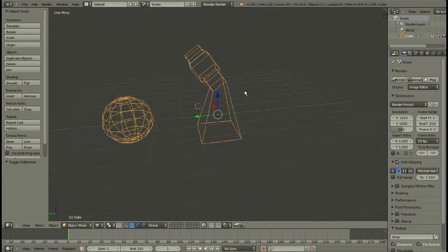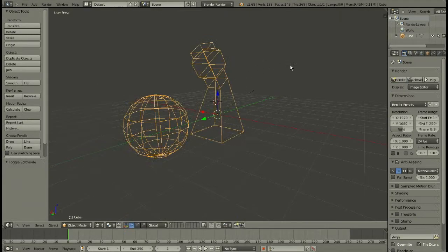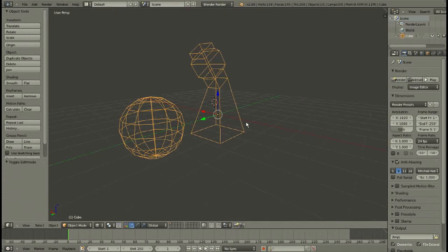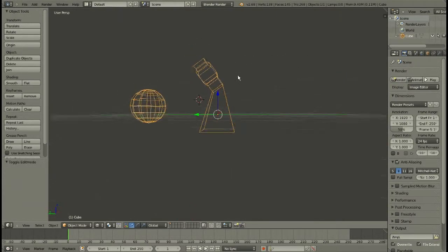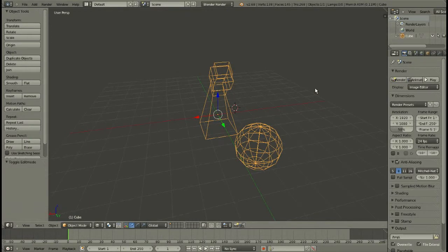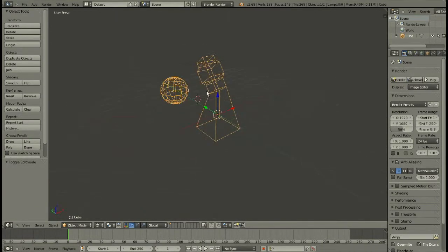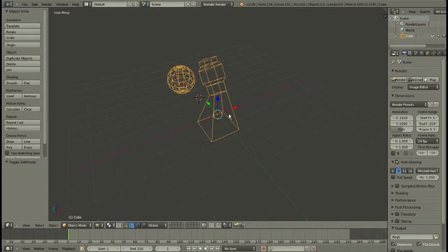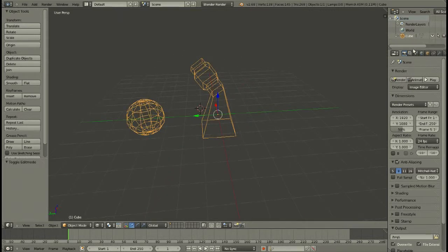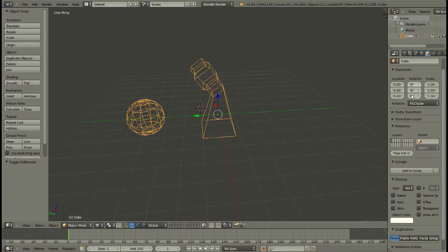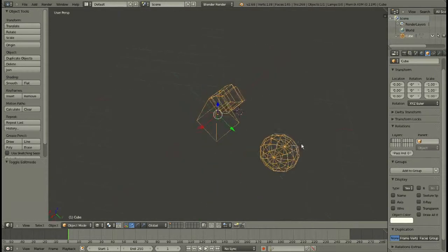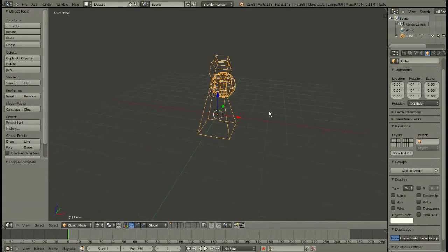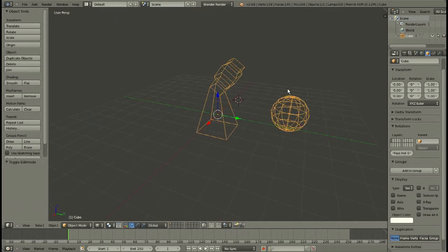In object mode, of course, you can still do things like scaling along the x-axis, scaling along the y-axis, but generally it's better to do that all in edit mode, because a lot of things require a 1 by 1 by 1 scaling ratio, so they don't preserve the natural scaling. So you want to have everything done in edit mode. For instance, over here on the side, I can edit these things and make it rotated in object location, rotation and scale, but that is applied after the vertices are assigned their position. So it's kind of like a modifier, something that happens after the fact.